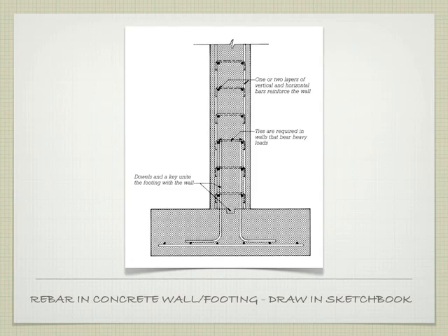Yes, sir. Exactly. So you would have a set of drawings from an engineer that would say this is where the rebar is going to go. So when you pour the footing, you would intentionally put those so that they match up with where the rebar in the wall would go. So you would do that all at once. And if you think about the act of pouring the footing, it actually needs to be fairly precise so that these pieces come up where they're supposed to come up.